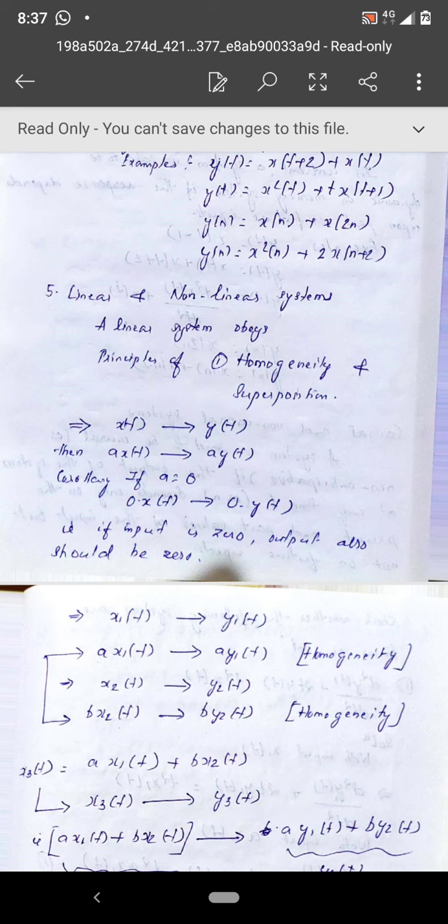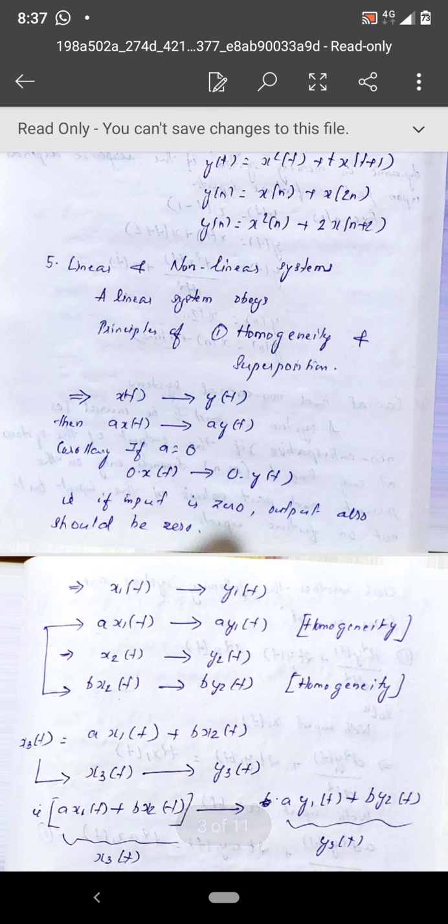So the first check you have to conduct to ensure whether the system is linear or non-linear is the principle of homogeneity. That is very easy to perform. That is why we have to check that. If the principle of homogeneity is violated, then straight away you can declare that such a system is a non-linear system. So whenever you have a problem on hand, the first check should be the principle of homogeneity.